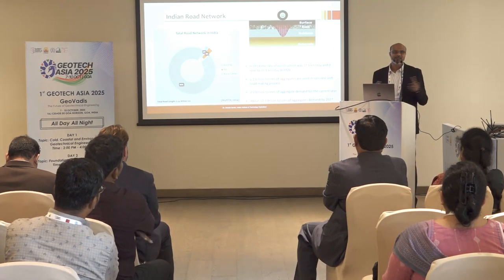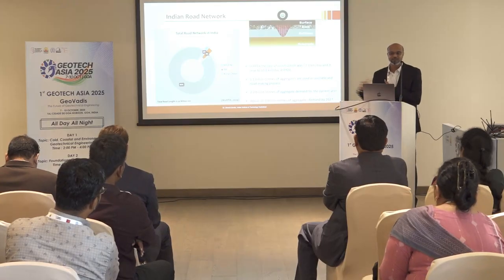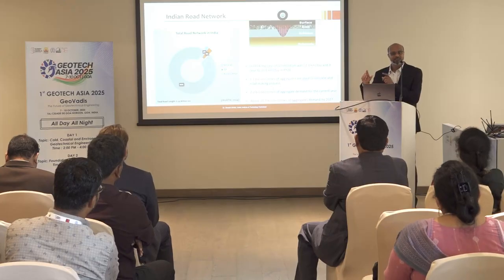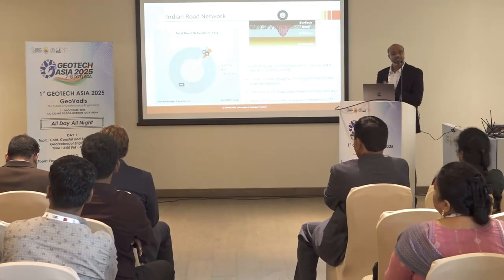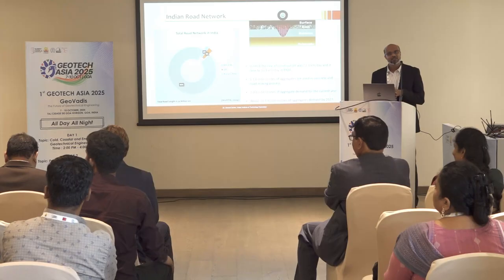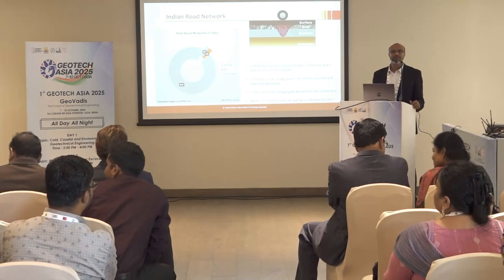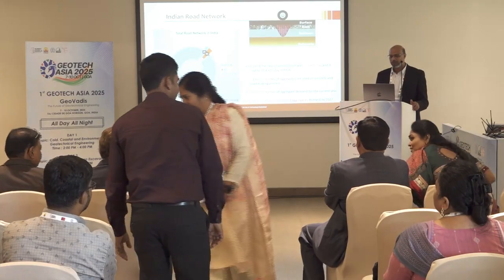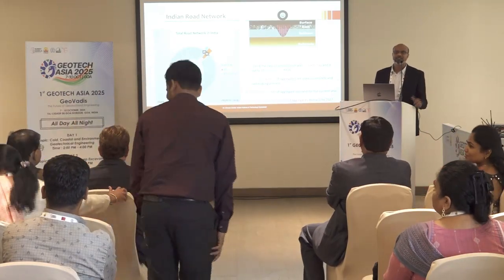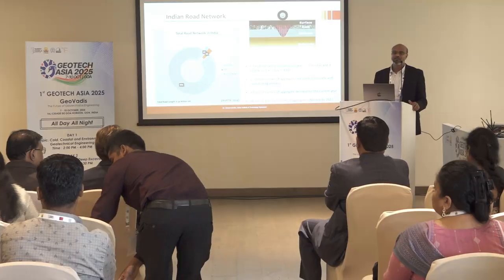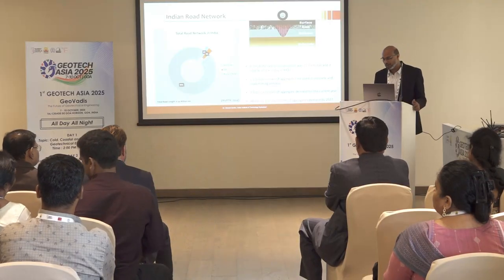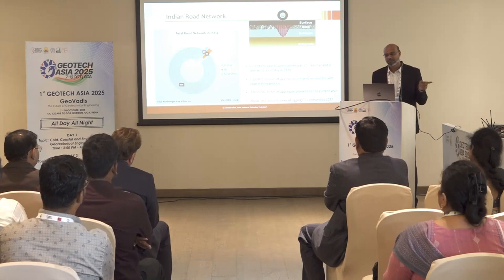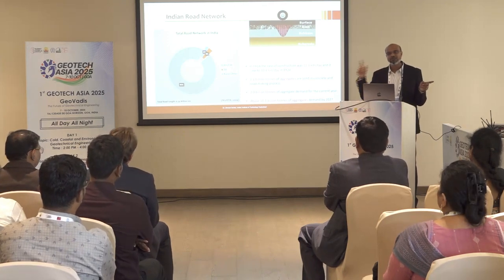And if you count all the next 5-year plan, we have more than 1 lakh kilometers of national highways projects, which will need billions of tons of natural aggregates to be used. So the idea is how to reduce this natural aggregate and also make the pavements more sustainable. The idea is not just cradle to grave, but how do you repurpose it?